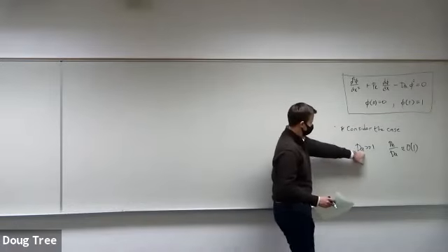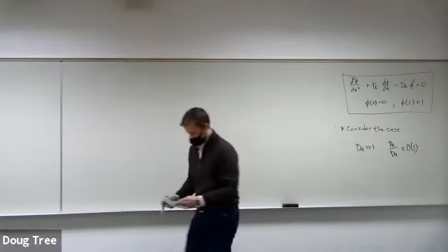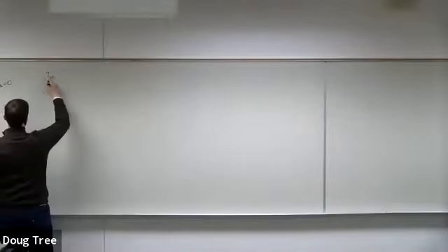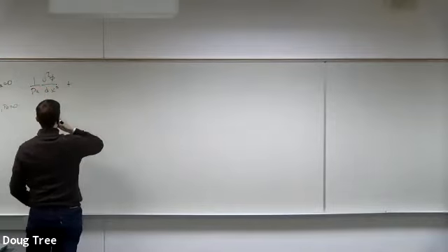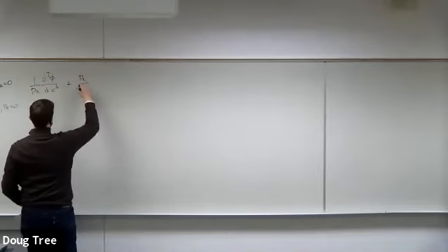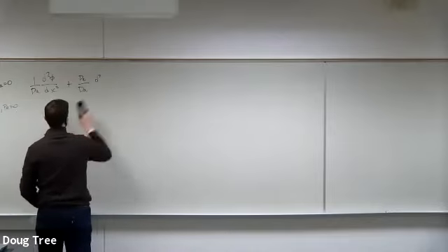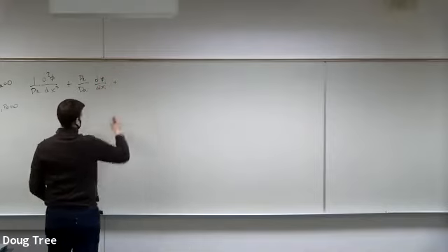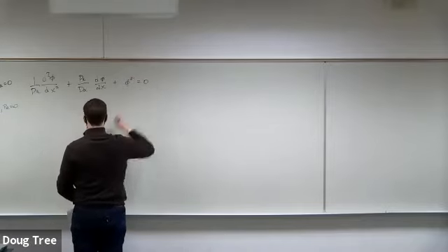So if the Damkohler number is big, then I want to divide by the Damkohler number so I get small numbers. So I'm going to divide every term by Damkohler. So I'm going to have d²phi/dx² with a 1 over Damkohler in front of it, plus, and here I have Peclet divided by the Damkohler number, and this one's what? This one's just a single derivative, dphi/dx, and then the last one should just have nothing. I think I missed a sign.